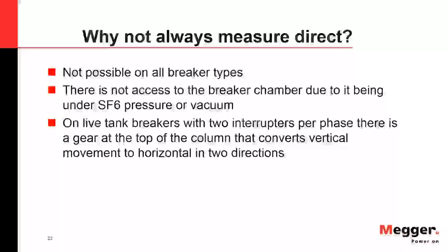And depending on the type of circuit breaker, if that transducer is sitting on top of the circuit breaker or is up in the air where there are live parts, you really can't have a transducer up there because it's going to be live and you can't isolate the cables and all that. But I have seen where people have hooked up a rotary transducer somewhere safe below any of the high voltage parts, and been able to run a test while it's live.